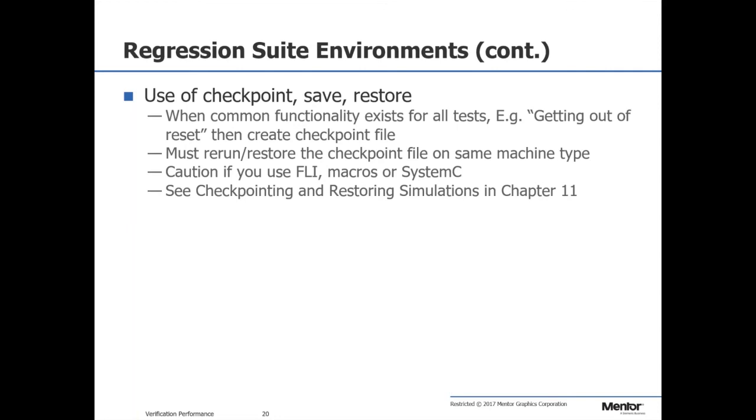So if you change one line of code, now the restore state does not match the state space of your design. So what you need to do is be creative and say, okay, I've got to tell the simulator what test to run. And maybe you do that through a force command, or you read a file, or you do something. But if you have a simulation where you have this long training phase, this can be really helpful.